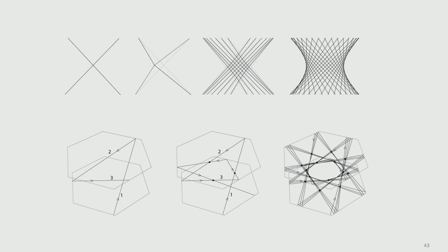So the component is winded by iteratively laying fibers, running in circles basically around it, on top of the steel frame. And as a result, the time-based winding syntax plays a really crucial role, since each fiber tensions the previously laid ones. And the hyperbolic shape is a direct result of the definition of these points, in which sequence they come together.